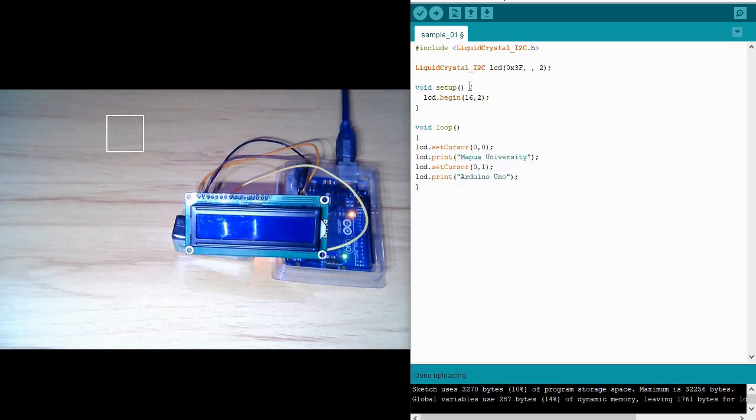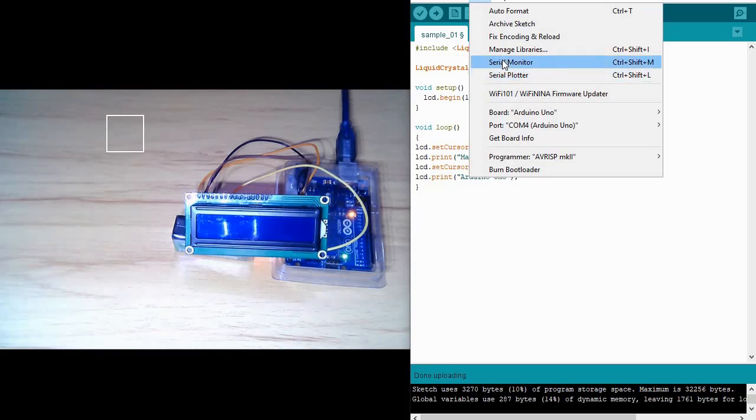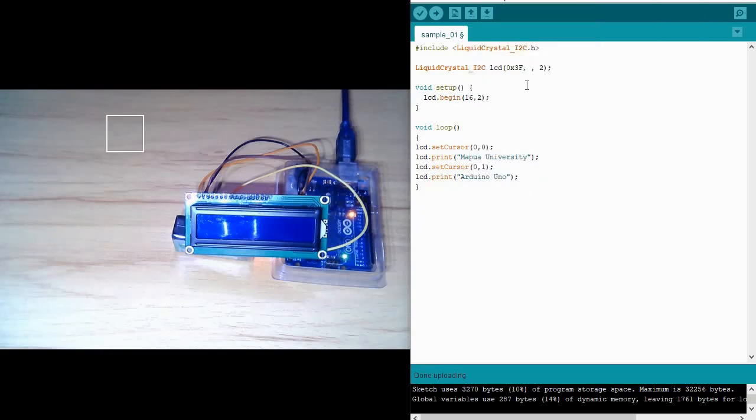So there are some scanning codes that can be used in your Arduino. Just connect the I2C as is in your board, and then you need to run the scanner and open your serial monitor, so that you'll be able to specifically determine the address, followed by the size of your matrix.